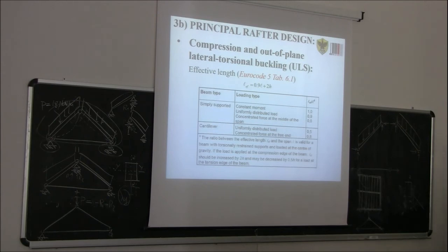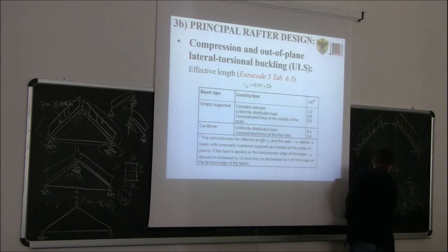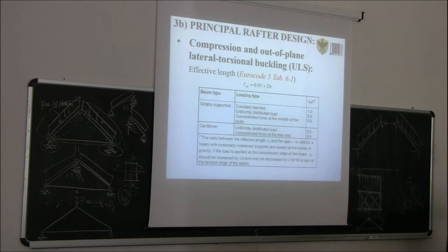This is not a huge structure like last time, 20 meters by. This is a small structure. It's two pitches, so we're talking about, I think, 4 meters by 5. So we could think about putting, for example, a bracing like this: one cross bracing on one pitch and one cross bracing on the other pitch. If I do it this way, which kind of deformed shape can I expect?